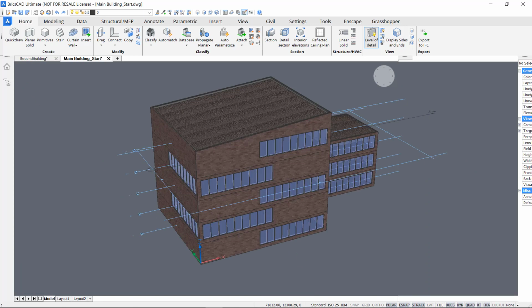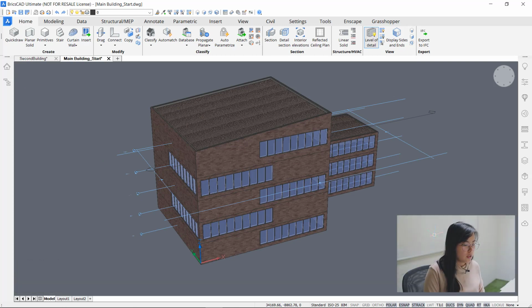So these are custom properties, and this is the end of the module adding BIM data. So you have seen how the structure browser works, how classification works, how to add in compositions, and then auto match it to your own drawing or an external drawing, and afterwards also add in properties as well. I hope you learned something about it, and thank you for watching.